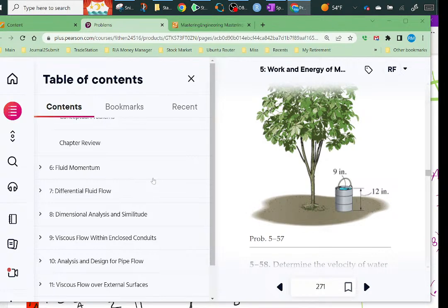We analyzed this. We thought this was going to happen. It did happen. We were lucky, because now we can scale things. You can take a scale rendition of something, put a different fluid in it, and run it differently. The only problems I've ever seen in fluid mechanics deal with ocean-going vehicles, because you'll have a viscous drag because of viscosity, and then you'll have a wave drag, and you can't scale them both the same way. They don't scale. And they could, if someone found a working fluid that would scale perfectly.